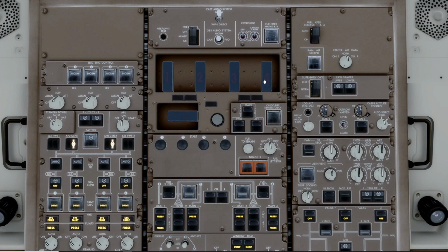Push the fire switches in. Of course, we can't do that in a virtual simulator, but just make sure they're in. No lights here, APU fire switch in, no light. Cockpit area microphone. These switches should be off and blank indications, guard closed, blank indications. Start switches all in, we just push to make sure.